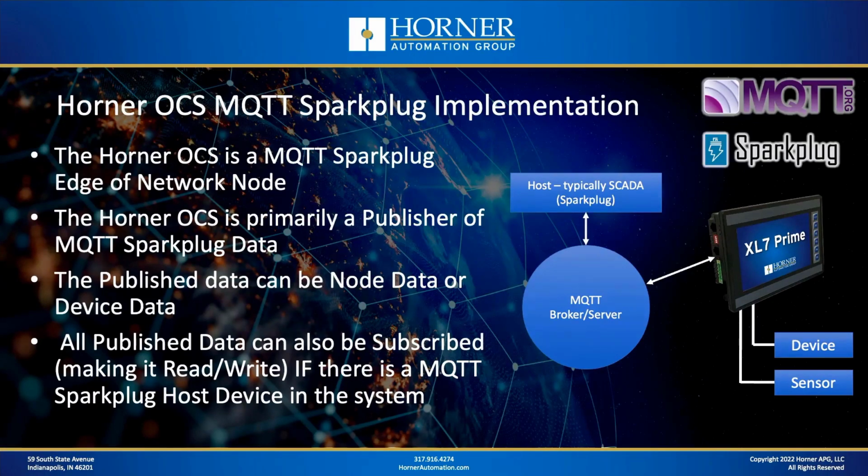And then this is an important point to be aware of. Another role that the host plays in a Sparkplug system, remember, that's the SCADA type device, if you will, is that the host manages the published data to the point where any data that the OCS publishes, if there's a Sparkplug host in the system, that data also is automatically subscribed. In other words, the data the OCS is providing to the network as write-only data, if you will, becomes read-write.